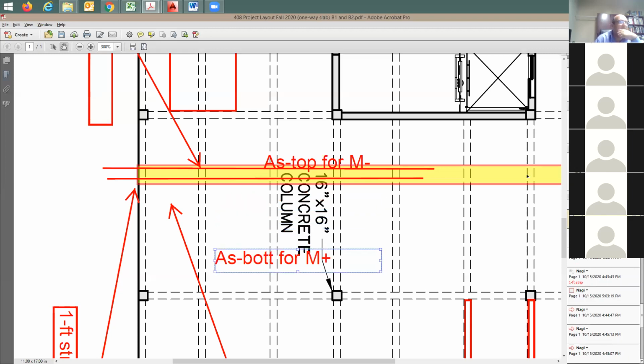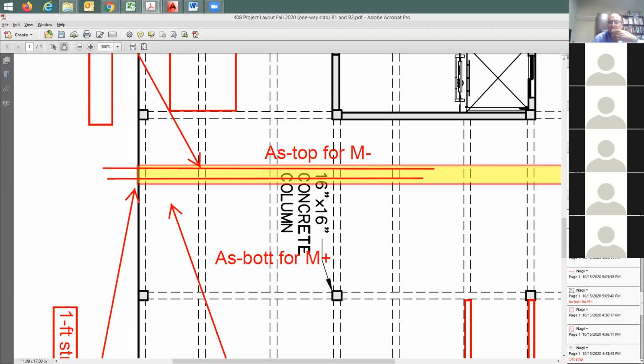So in your beam analysis, you need to look for the maximum moment at the bottom, right? The maximum moment here at the bottom. Just take it and design the section. Are we good? Questions? Same thing for the top. At the top, you're going to be looking for the maximum negative moment, and then you design the negative, or the top, reinforcement for it. Questions?